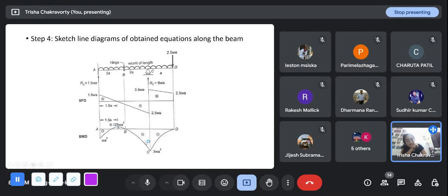So to sketch this diagram, if you didn't find out this and I told you to join these by a parabola, you'll probably do it like this, you will probably keep the entire thing as negative. So to sketch the bending moment diagram, it is always recommended that you solve the bending moment at 2, 3 points, and definitely at the point where it will be maximum. So first thing you do is put dM/dx equal to 0 and find out the x where it is maximum and find out its magnitude. From that you will get a fair idea, and it is advisable that you solve at 1, 2 other points to see the nature. And bending moment here is 0.